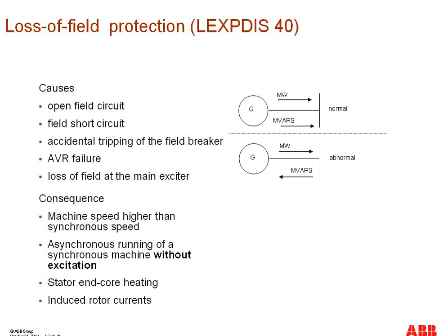So let's talk about the loss of field protection. The IEC 61850 logical node for loss of field protection would be LEXPDIS, and the ANSI number is 40 for this loss of field protection. There are several causes of the loss of field.